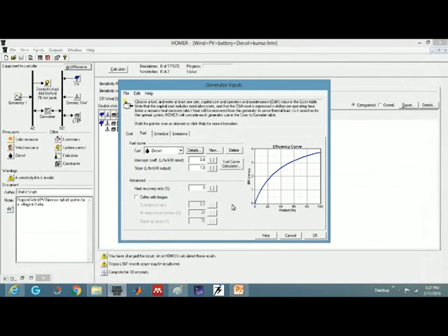And we are not supposed to run it at full capacity. Suppose I have a generator of 1 kilowatt and I need 0.5 kilowatt power. So I'm not going to run it at 1 kilowatt. I'm going to run it for 0.5 kilowatt. So what will happen in that case? The fuel input will be different, and that is a non-linear curve, right?